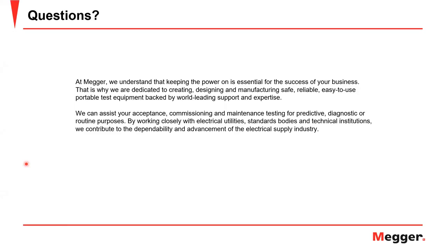And you can, I would say, selectively activate the single phase and the three-phase reclosing of the recloser system that you are using. So the answer to that question is, you need to verify with a proper load and fault study, and with the types of loads that you have connected and the service level agreement you have with those customers, whether it is a good solution for you or not.